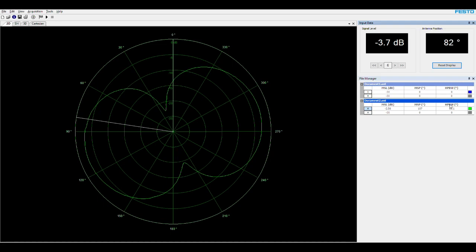Now that we are done, in the next experiment, we're gonna be measuring cross pol E-cut, E-plane. So essentially, I now need to rotate the transmitting antenna 90 degrees to create that polarization mismatch, and I'm gonna perform the same experiment again under polarization mismatch, which would be cross pol E-cut.